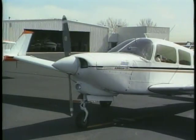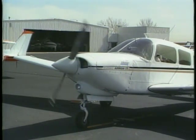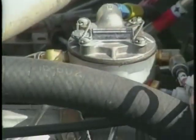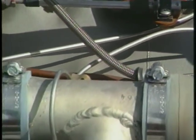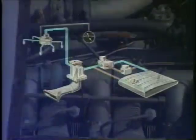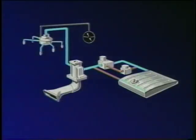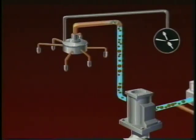Vapor lock occurs when vaporized fuel blocks the flow of liquid fuel to the fuel injection system. The reason fuel injection systems are more likely to experience vapor lock is because there are more fuel lines in close proximity to the engine and the heat it produces. If temperatures are hot enough, the fuel inside the lines vaporizes, resulting in low fuel pressure or engine failure due to fuel starvation.